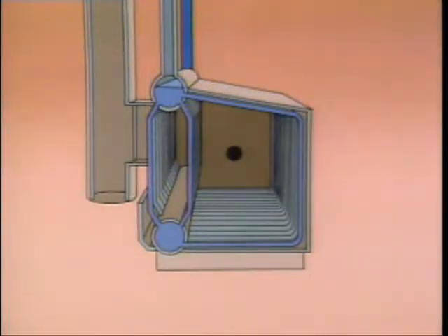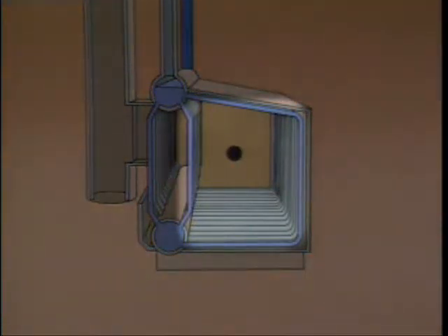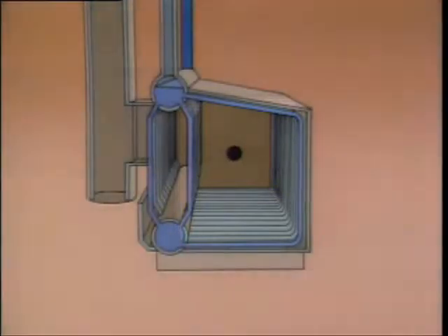This particular boiler consists of a series of water tubes and 2 drums. The drums distribute water to the tubes. The water tubes connect the drums and form a wall around the combustion area of the boiler. This is where heat is generated.